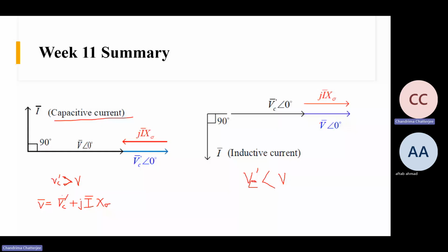Another important aspect is the control characteristic. Here, the control characteristic of STATCOM is presented, and the control characteristic of SVC is this. So there is a difference. The control characteristic can be horizontal to the x-axis, or there may be a very slight positive slope. By implementing this, we get certain advantages, by having a slightly positive slope.